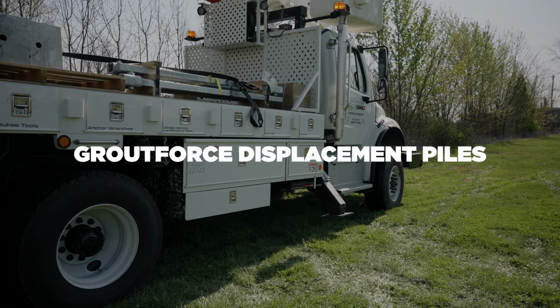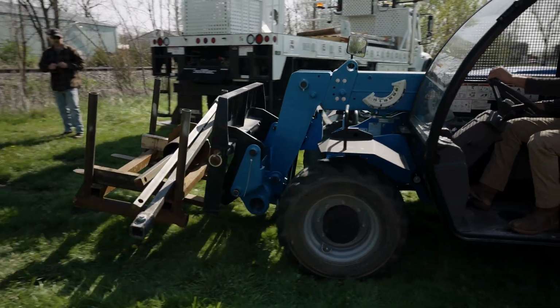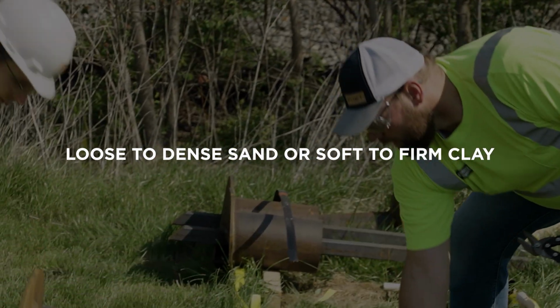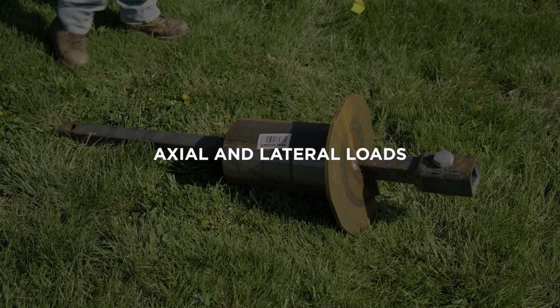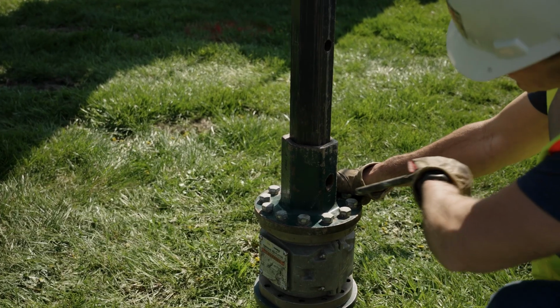The Chance GroutForce Displacement Pile, or GDP, is a patented foundation solution excellent for use in loose to dense sand or soft to firm clay. GroutForce piles provide significant axial and lateral load capacities and can be installed to over 500 kip.